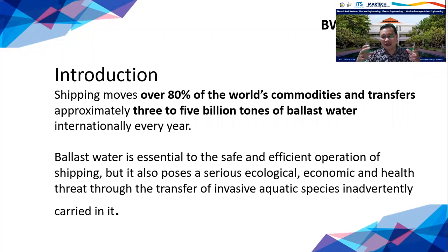On the other hand, ballast water also poses a serious ecological threat. Therefore, it is necessary to carry out some treatment. One way, as I mentioned previously in the video, is conducting ballast water exchange, and the second one is ballast water treatment.